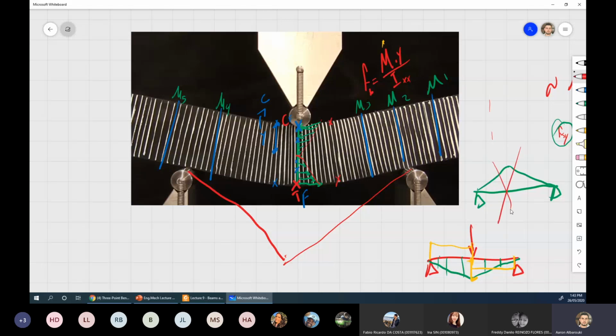We will get over this sign convention for structural analysis only, for structural engineers. That's not for engineering mechanics. That's for structural engineers. What we usually do, we agree on bending moments acting. The bending moment positive is sag and negative is hogging. And usually we draw the positive down and the negative up. That's what we usually do.